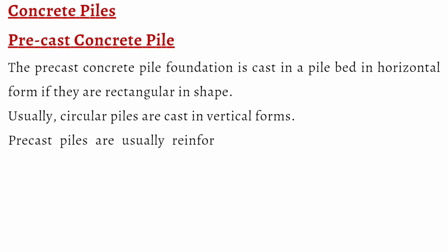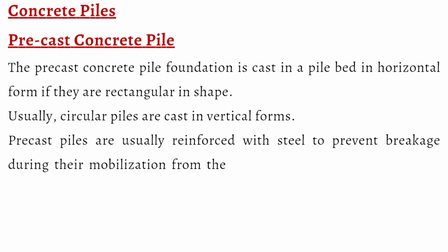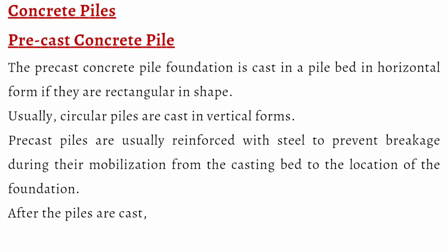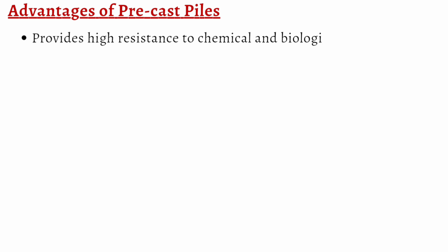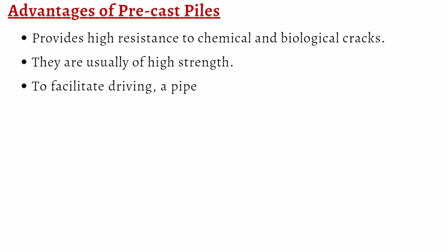Disadvantages of timber piles. Piles of longer lengths are not always available. It is difficult to obtain straight piles if the length is short. It is difficult to drive the pile if the soil strata are very hard. Splicing of timber piles is difficult. Timber or wooden piles are not suitable to be used as end-bearing piles. For the durability of timber piles, special measures have to be taken. For example, wooden piles are often treated with preservatives.